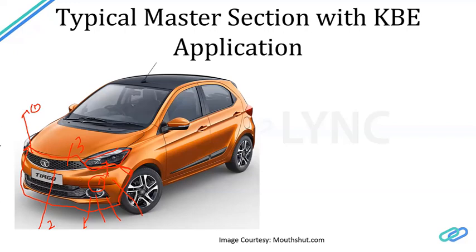So when I start the modeling approach on the complete bumper assembly, the first and foremost step, when I get this complete styling, I'll be creating a section, the Y0 section, where I will decide on what should be the clearance, how the parting line is derived, what are the manufacturing processes used for each part, and the gap and flushness conditions between the different parts of the vehicle. Depending on that, I will generate the inputs required to create each part.